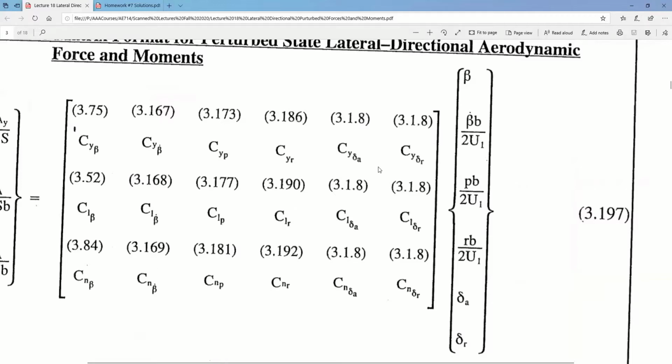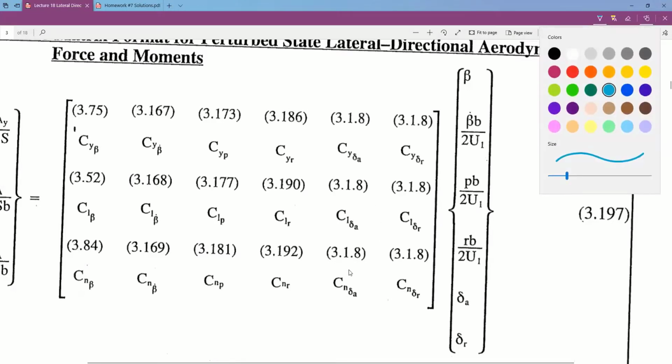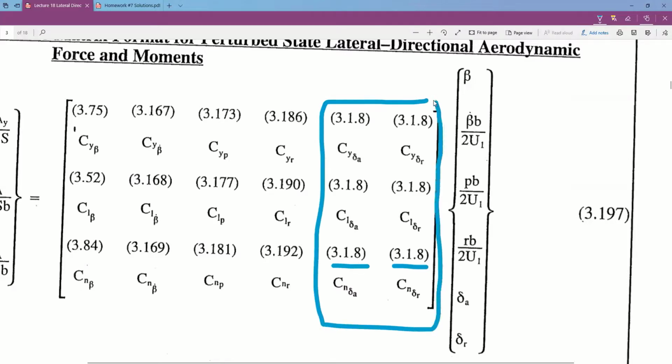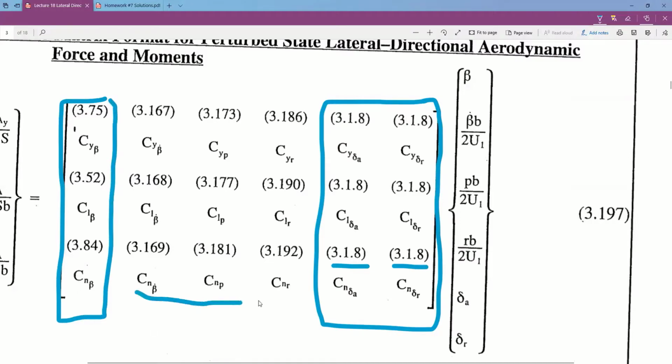We defined a positive aileron and how an aileron produces a roll and a side effect of a yaw. So those equations are back earlier in chapter 3. And the nice thing about this is he lists the equations that predict each one of these. So we're done here. We did this earlier, and we even did see the beta effect earlier. And so we just finished all of this, but this was enough. This is pretty complicated because of all of the coupling and the pieces and parts.